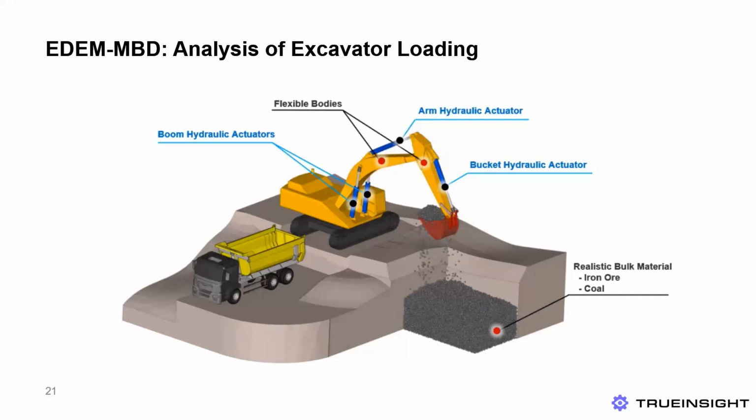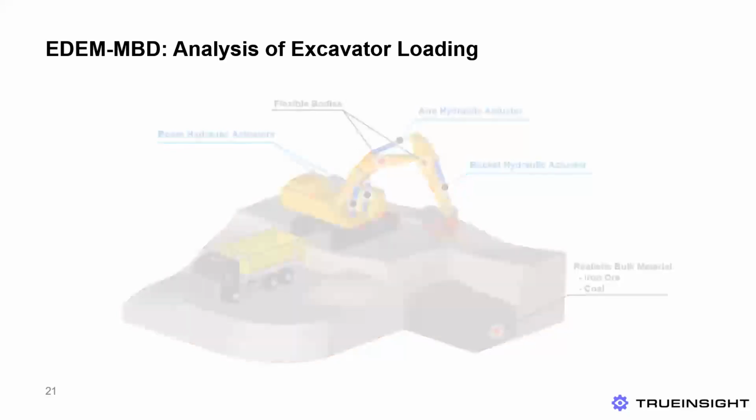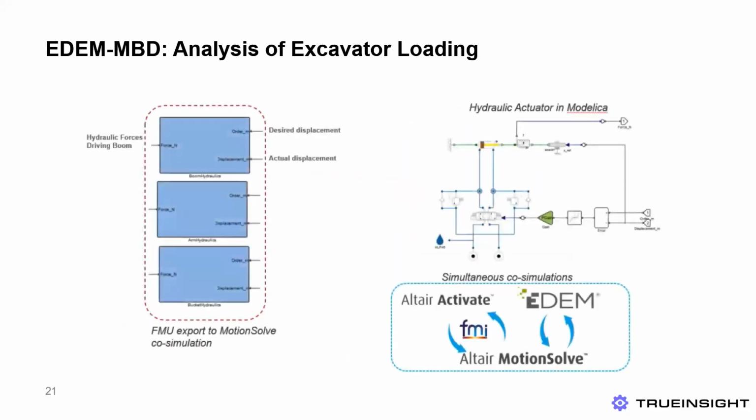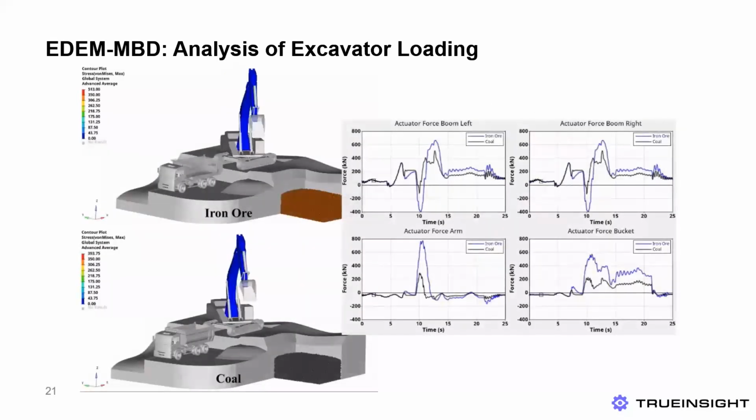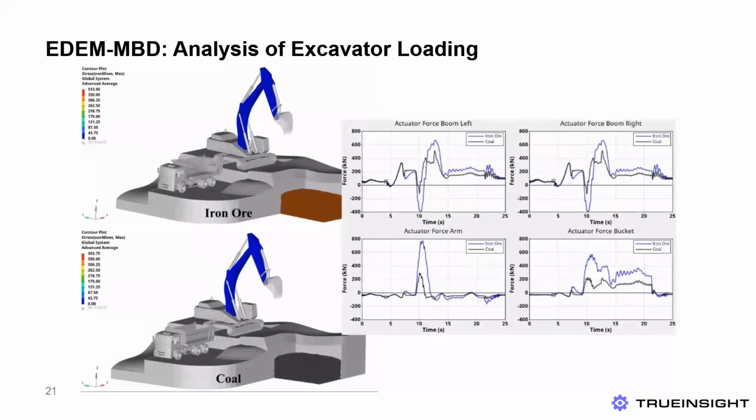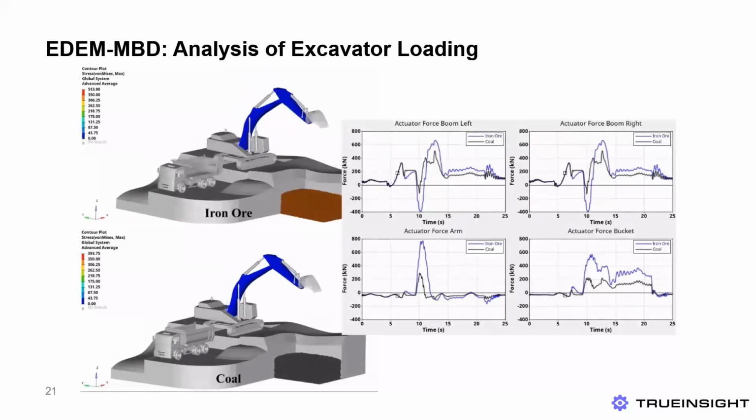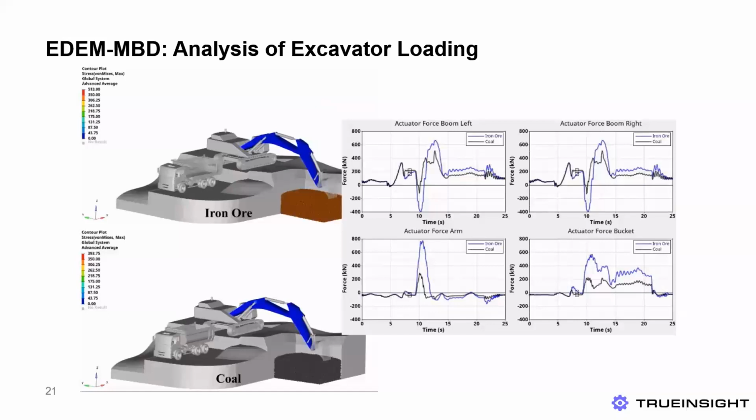For this analysis, the hydraulic actuators were modeled in Activate, and the motion of the boom was defined in Motion Solve, based on the loads generated by the hydraulic actuator and the resultant loads exerted by the bulk material in EDEM on the bucket. During the simulation, information is continuously being passed between EDEM and Motion Solve and Activate.